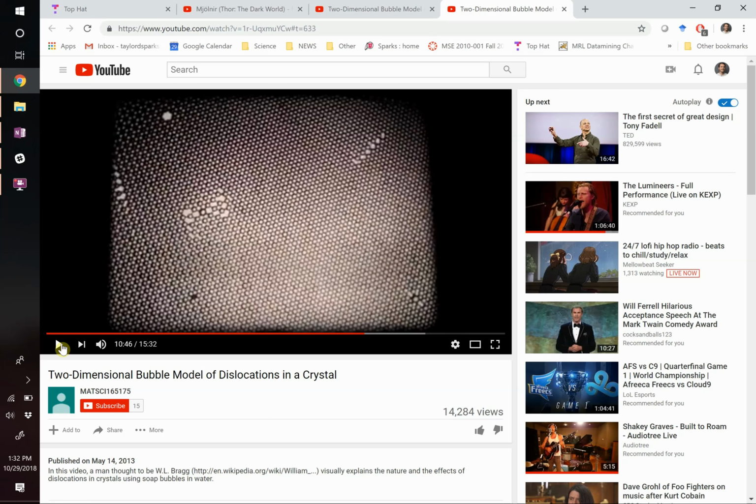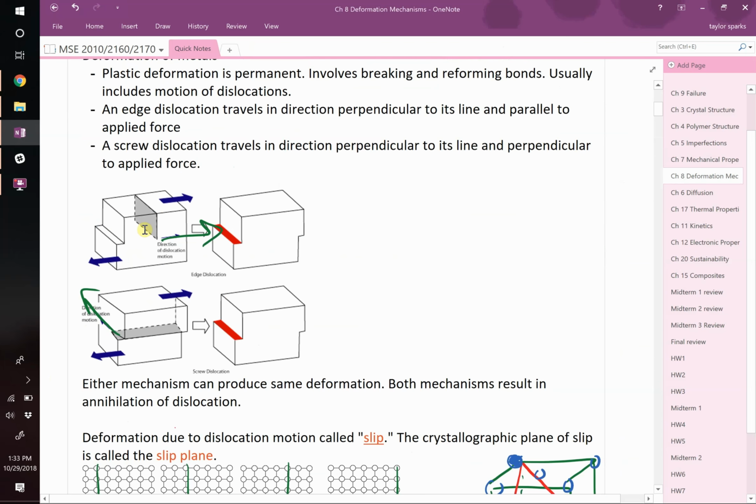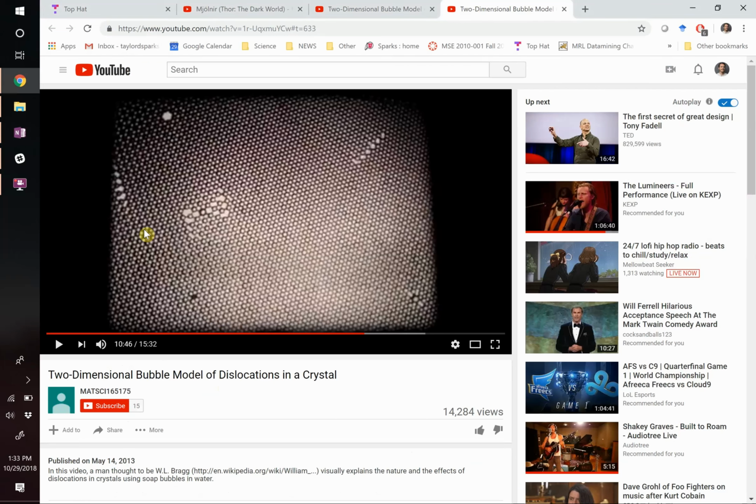We started this class showing how deformation occurred, right? If we go back to it, deformation happened like this. We said in order to get this thing to pop out at the end, which is a scratch or a dent or a breaking, this dislocation either had to move that way because it was a screw, or the edge had to move that way. But in either case, the dislocation had to be mobile. It had to move to create that deformation. And if you have this scenario where those dislocations are what we call pinned, pinned dislocations are dislocations with reduced mobility, you have a harder, stronger material.